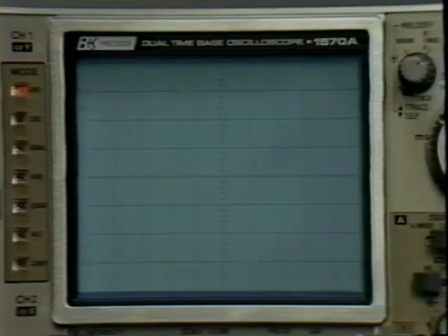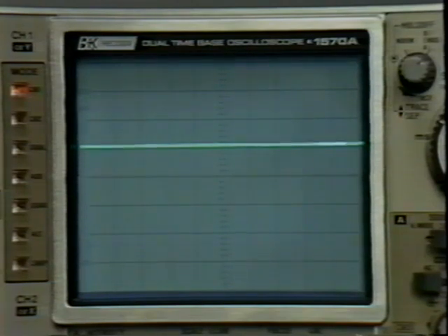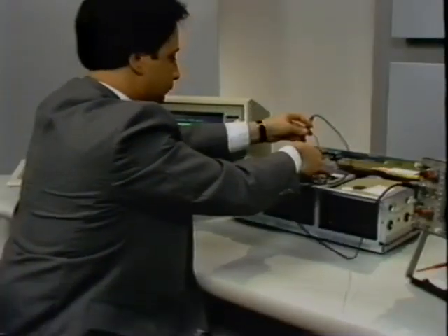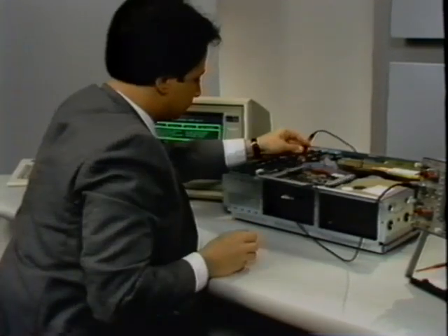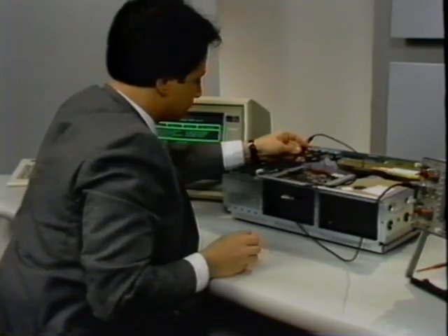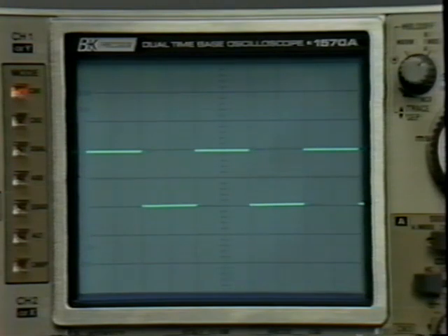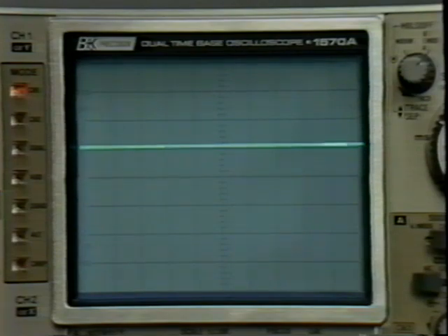If the level of the signal changes, the scope will display a varying trace that represents the changing value over time. If the signal level is stable, the scope will display a steady line representing that signal's voltage in relation to ground. There are several features of a signal that we can determine using the graph displayed on an oscilloscope. We can observe the waveform of a signal simply by looking at the graph. We may see a square wave, a DC level, or a pulse.